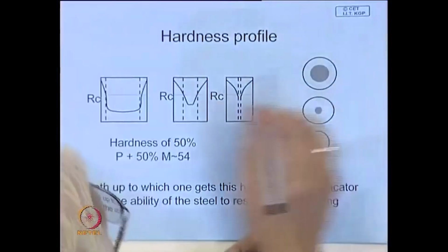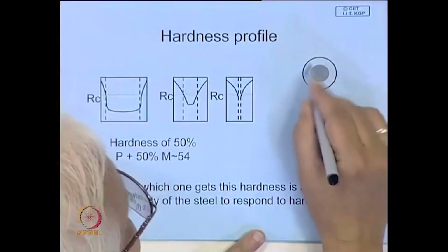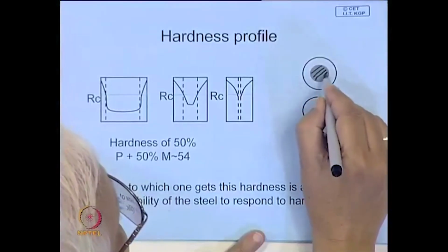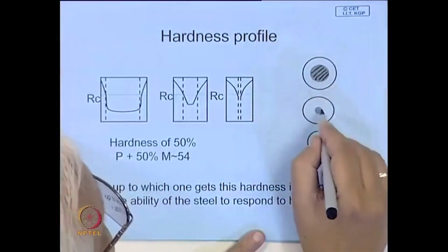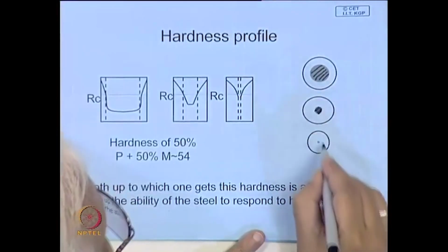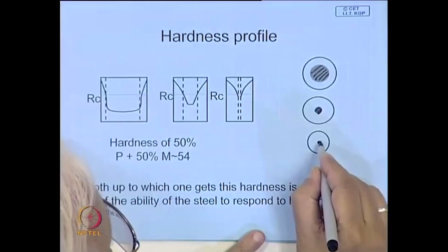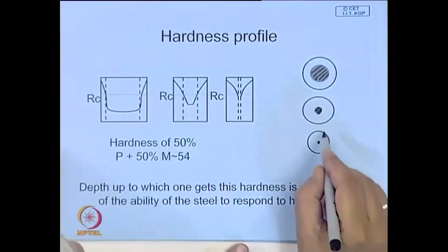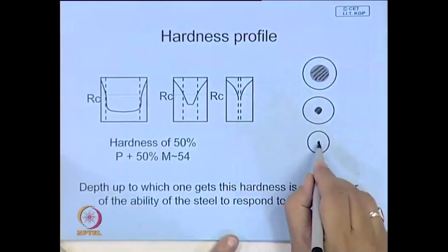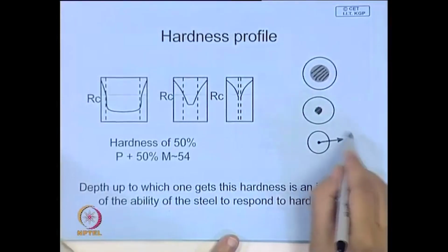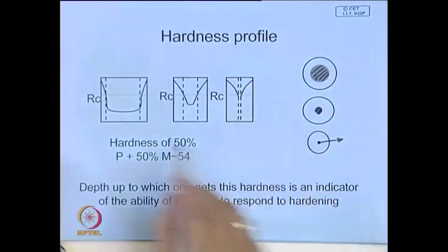You will find, say suppose here, this is a little larger diameter, here you find that this is the portion where it is pearlitic structure, ferrite pearlite. If the job becomes smaller, you will find this is the size. If you make it still smaller, this. So, in this way you can attempt to find out the diameter where this disappears. This just disappears.